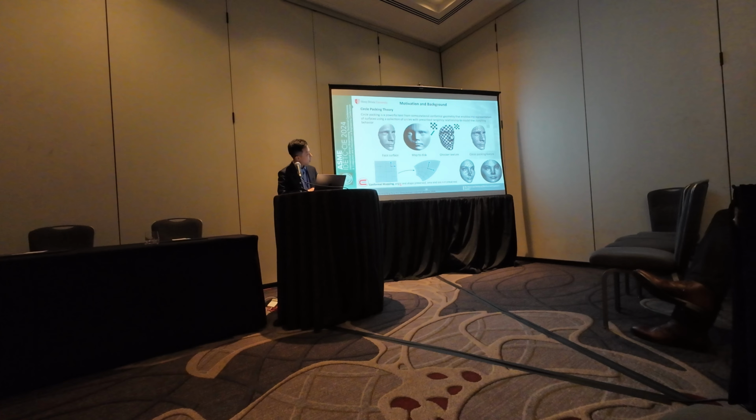We can start with this picture, which shows a flat panel to a hemisphere covered by circle packs. We leverage circle packing to model the moving behavior, and then conformal mapping is employed to deform the circle pack surface between 2D and 3D configurations, where the angles are well preserved. For example, in conformal mapping, from the initial shape to the target surface, angle and shape are preserved, but area and size are not preserved. That's a characteristic of conformal mapping.